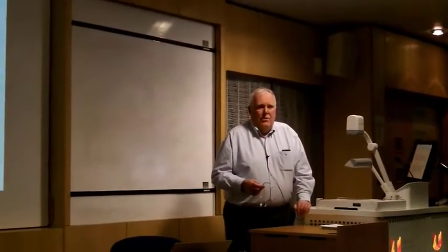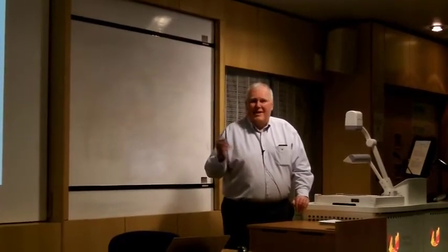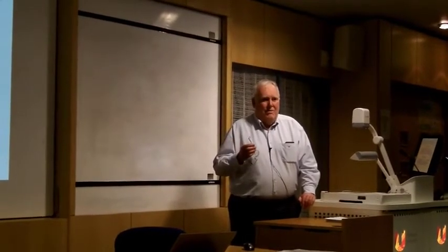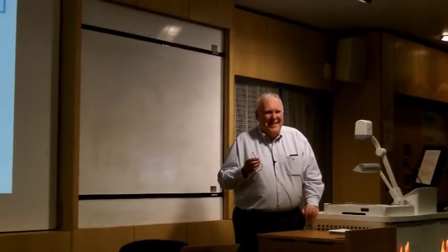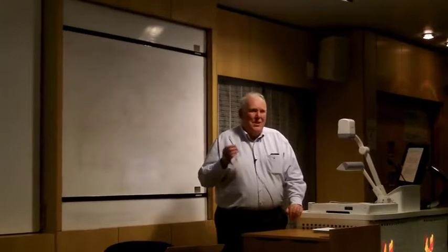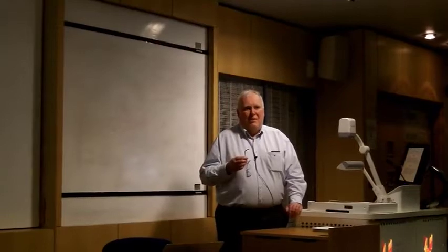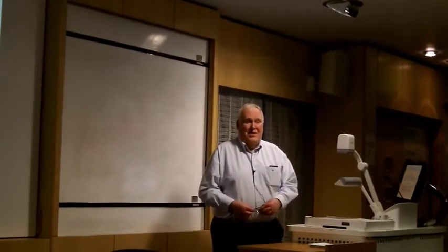I mean, I know some people. What I would be inclined to do is have a first relief valve set at the lower figure, and then I'd back it up with another one. I wouldn't like to put my reputation on the whole thing, but I think what it is indicating is that with dynamic simulation, it opens your eyes a little bit to what is really happening. You can imagine what's happening because you know that the temperature's going up in the column, and obviously the heat going in is going to go down. But it's hard to put a handle on it without spending a lot of time.